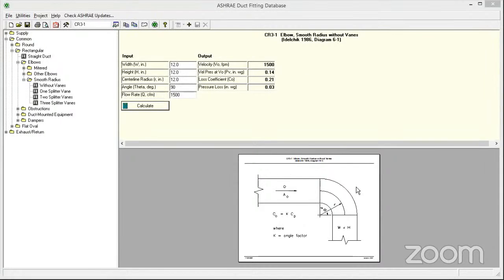Okay, okay, yeah. Regularly, what happens is in our projects, mechanical engineers sometimes they give these values and sometimes they don't. So, like, I suppose based on the values, either we can give them or we can leave it to auto size. It is always better to get precise value. So if they are not giving, then you are dependent on rule of thumb value. Because before ordering your fan, any equipment, you might have considered that pressure drop is less. You might have considered hardly 2 or 3 elbows, but on site you discover that 5 to 10 elbows have come up. So your fan will not be able to deliver air to the occupants. They might not feel comfortable.